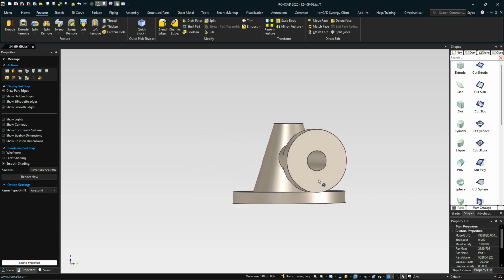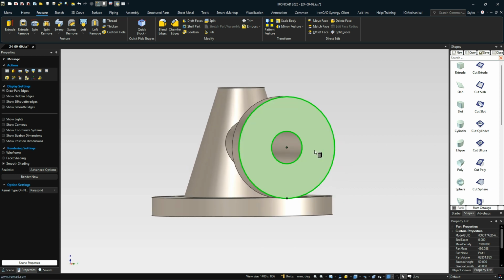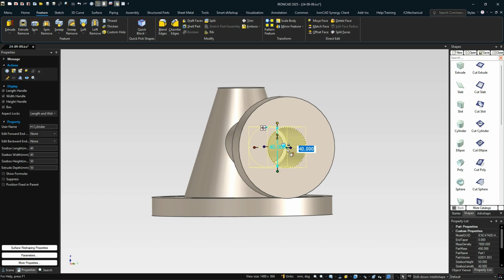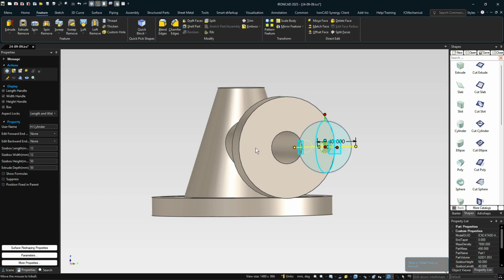Next, we can come over and do the same thing for a hole here. I'm just going to drop it right on the center point, and the thickness on that hole is actually 12 for the diameter, and we're going to move it out using the tri-ball. We're just going to move it directly out 40 because it's got a total diameter value of 80, so we'll just type that as 40. Oops, not 74. 40, there we go, to place that.